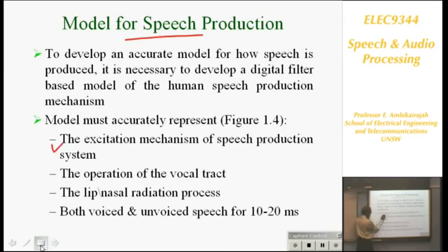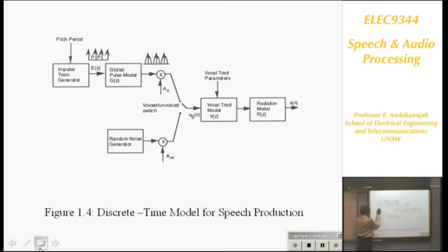The diagram consists of excitation, vocal tract, lips, and I decide voiced or unvoiced. So let me go to the next page. You will see, here is my impulse train generator, because I've decided I'm going to say a voiced sound, right? Then in the glottis here, as soon as you produce pulses, the glottis is a kind of a low pass filter. It actually shapes the pulse. So the pulse doesn't look like a sharp pulse, that's really ideal. You will find the pulses are shaped like that. But still the periodicity is maintained, still the period. And then its amplitude is adjusted by a volume controller.